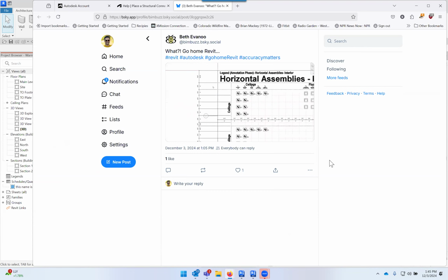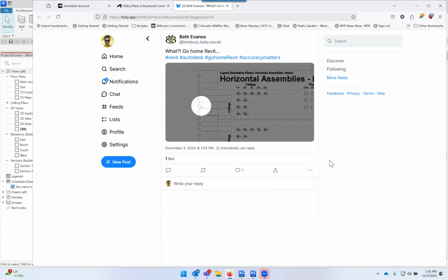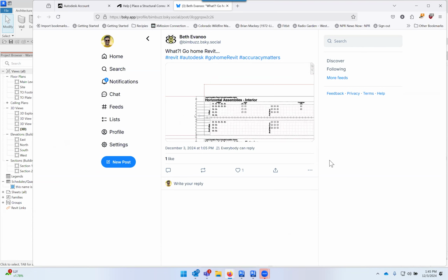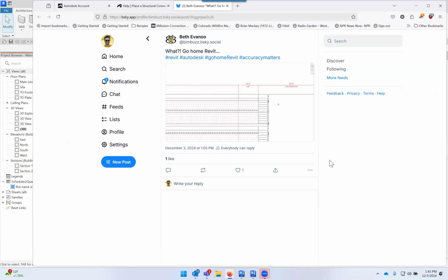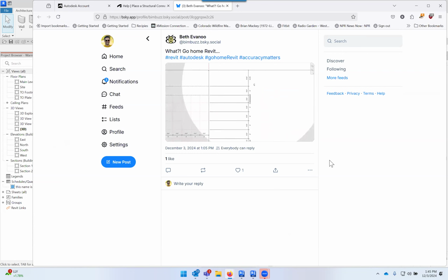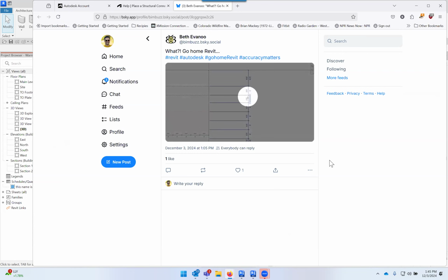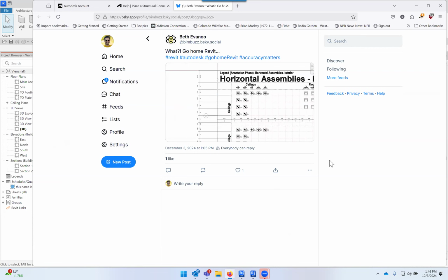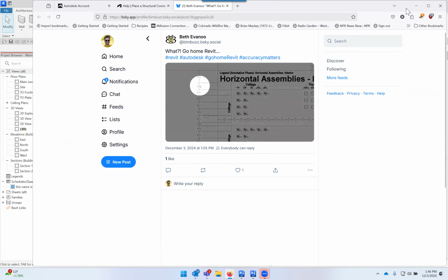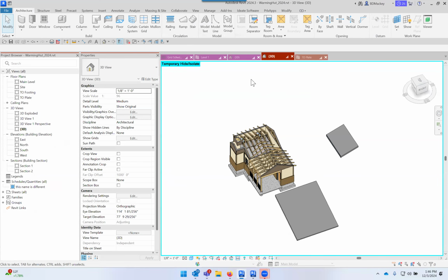You should still be able to go. I do not go out as far as decimals will allow, only because I don't go out past 10, Beth, because the computer rounding in Revit is pretty much only accurate to 10. I have found times where things will be perfect at 12 and then, with nothing changed, I open up the file and now it's rounded, it's different, and I get that bizarre number. So I only ever go out 10 decimal places because of the computer rounding issue. In my template and every file I work on for all my clients, I create what's called a working dimension. The dimension's orange.